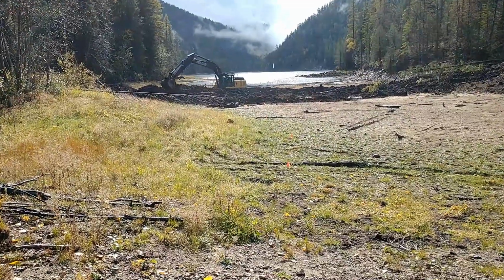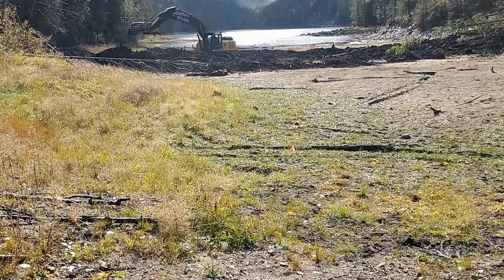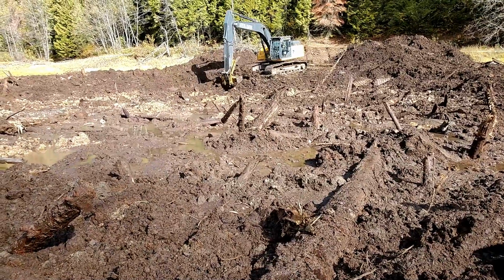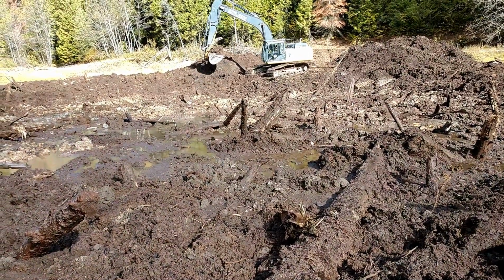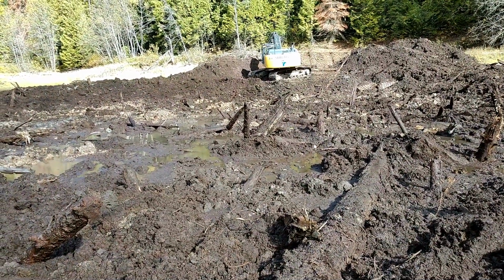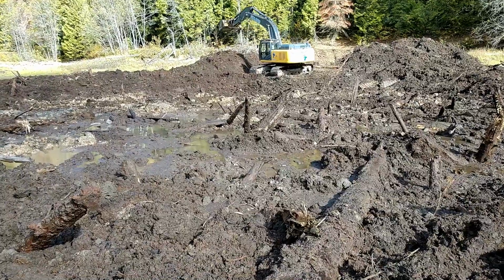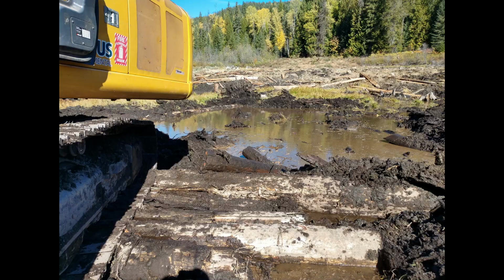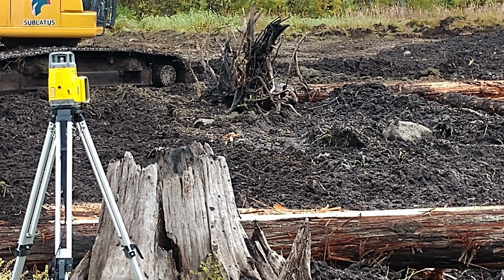The orange wire flags mark the perimeter of the wetlands we were building by using the groundwater technique. The wetlands were dug deeper than the elevation of water in the restored Violin Lake. The basins filled with groundwater as they were being built. The soil removed from excavating the basins was placed on higher ground that was open and not growing trees. Excavator operators used logs to keep from getting stuck in the saturated soil. We used a laser level to take elevations to help guide the excavator operators in how deep to dig.